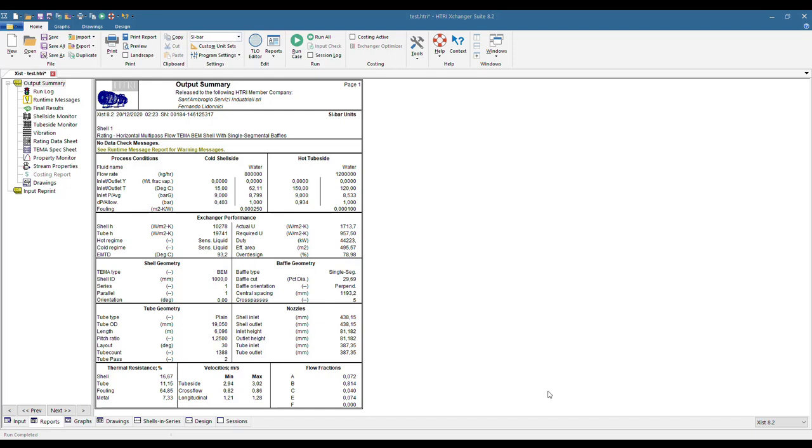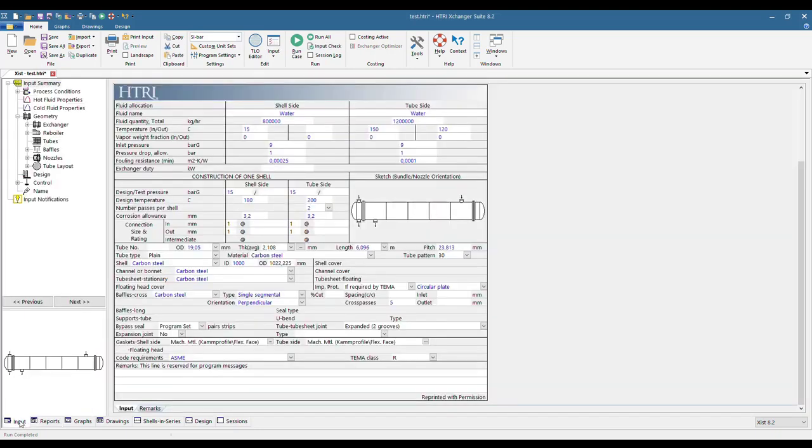Note, however, that generally speaking, the engineering companies do not like very much to have tube lengths which are shorter than the length they have specified. But generally speaking, if we reduce the length, cutting 1/2 of the standard tube length of 20 feet is generally acceptable. So what we have to do here, we go in the input, and instead of selecting